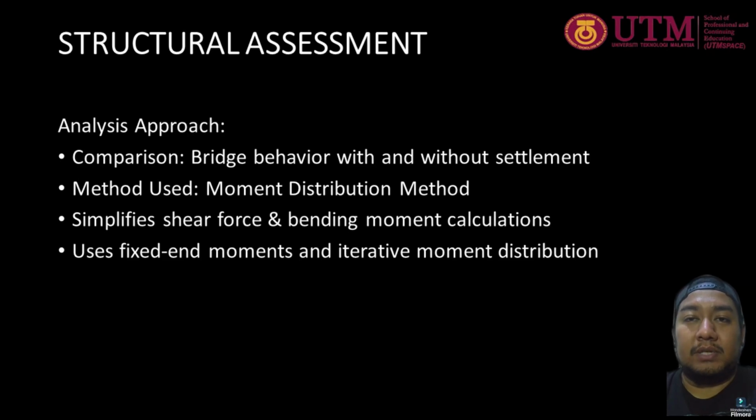Our investigation process involved several key steps. First step, organizing the investigation team to identify the necessary expertise and develop a step-by-step procedure to carry out the investigation. Second step is developing failure hypotheses, and we formulated 2 possible hypotheses for the observed settlement and cracks. First hypothesis, settlement due to soil conditions and foundation instability. Second hypothesis, settlement caused by material deformation under external load.